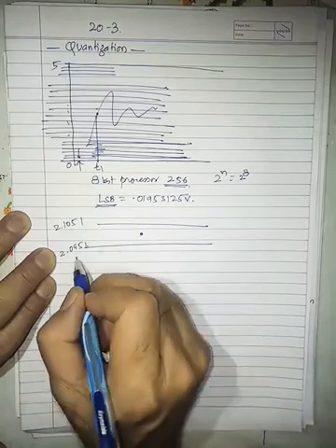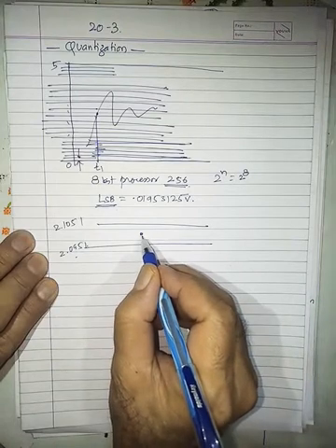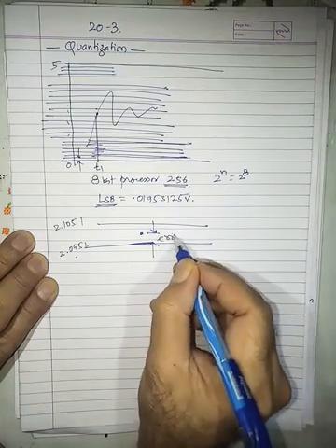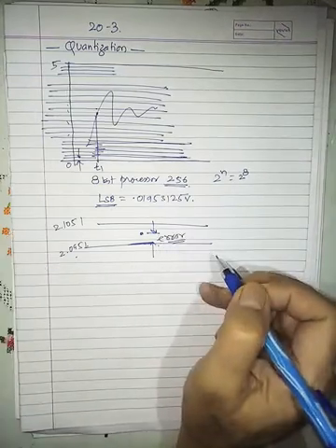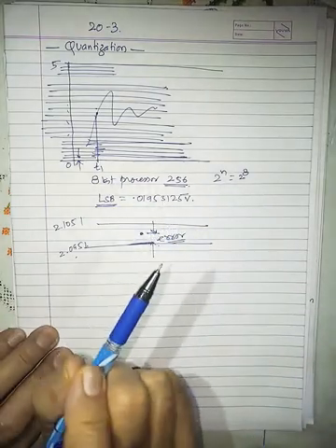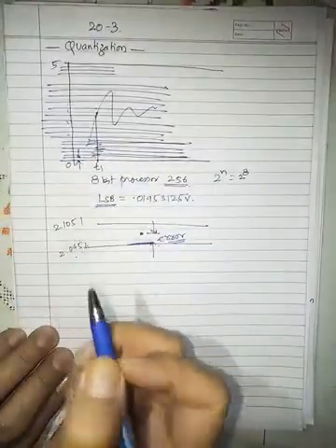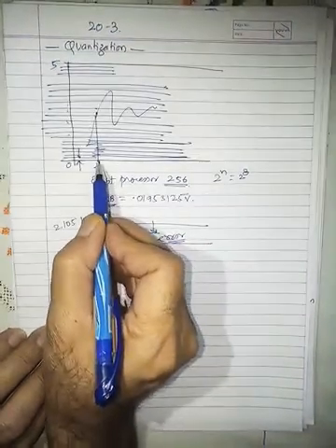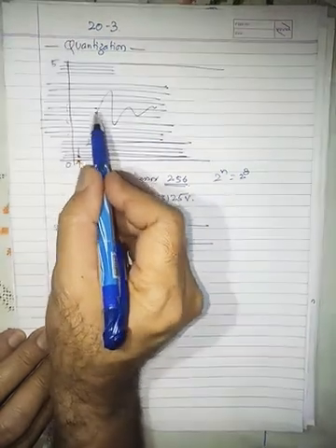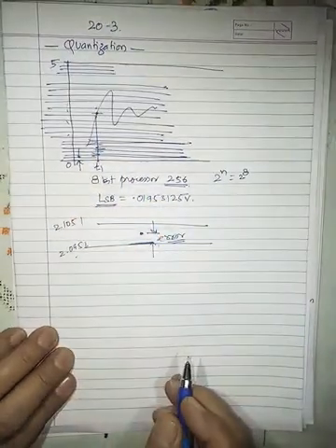So this signal is neither this nor this, so I have to round it off. The circuit will round off to the next level, that is this level. That means this much error is added in the circuit. In the quantization process, some error will creep into the system. Because of this, you may have 256 levels, but it is very much possible that when I take a sample to note down what the voltage was at T1, that point falls between two levels. So this is known as a quantization error.